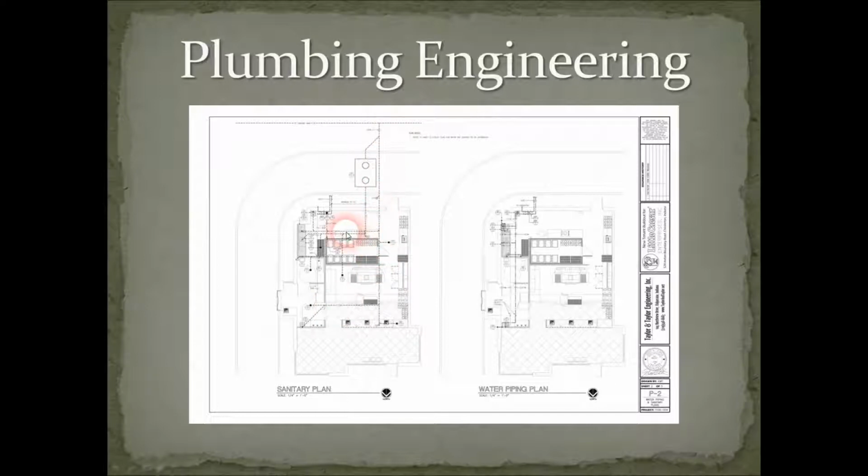In a restaurant type of kitchen here, a lot of this water will have grease in it, so it has to go through the lines and then it has to go through this big box that's buried underground called a grease trap, and that separates the grease from the water so that the grease does not get put back into the city's utility system. Every once in a while a big truck will come and it'll remove all the grease out of this grease trap.